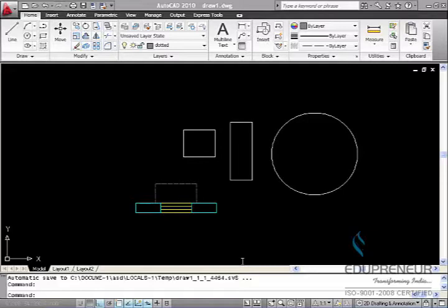As your drawing becomes more complex, these different layers can be turned on and off to allow easier display and modification. We will learn this in layers, which is a command in AutoCAD. The command is LA.